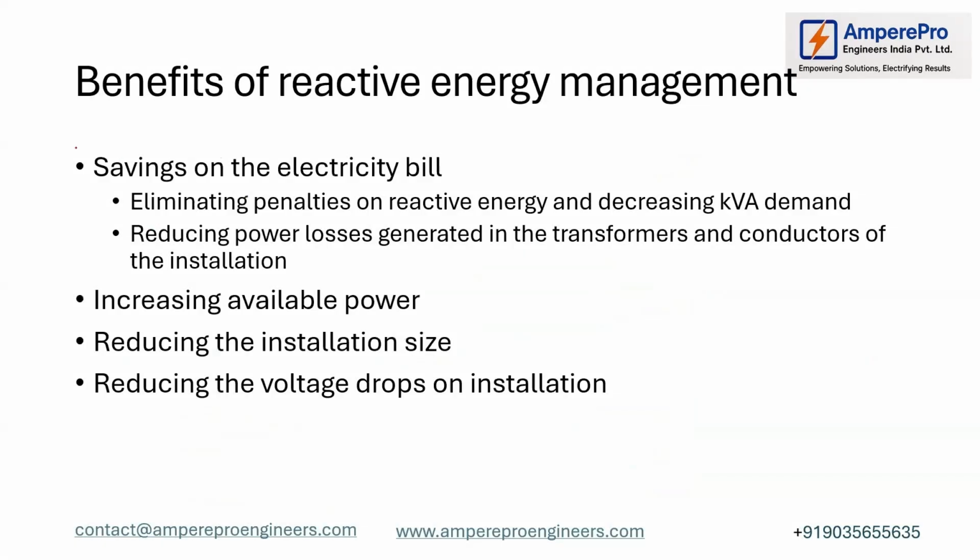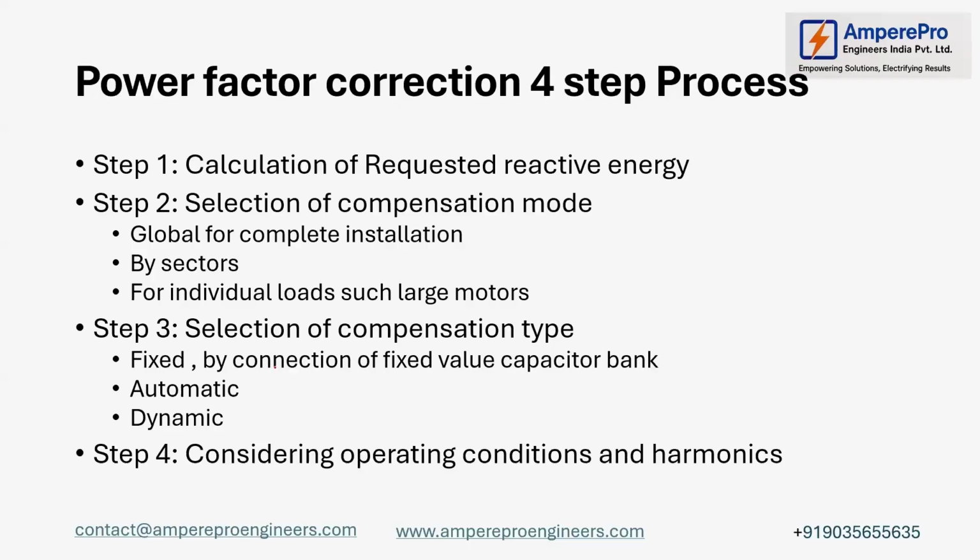So that's what is mentioned here. Let me look at this. This is the step-by-step process that I have given. One is reactive power, how to calculate that. Second, when you have different types of loads, you need to figure out where you have to put the capacitor bank, at which location. One is global compensation for the complete installation, which is what we have done now, or by sectors, or by individual loads. Let's see that in the next slide.